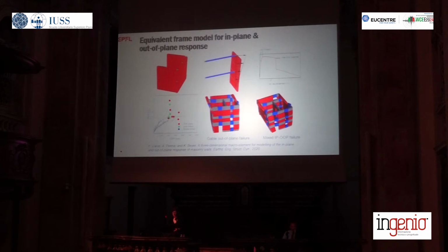Here you see a little bit of how that element behaves. For example, if you have a U-shaped wall and you do a pushover here, then you can really see the out-of-plane behavior. Here you see the force displacement response on the right-hand side, and you can also model that the beams slip off. This is of course rather important, because the connections, as you will see in a moment, are a very important modeling detail when we model the out-of-plane behavior.